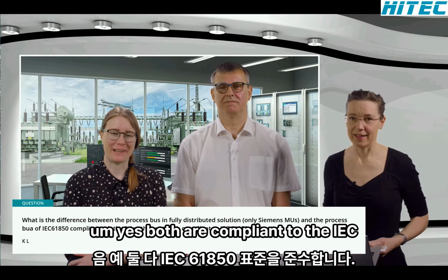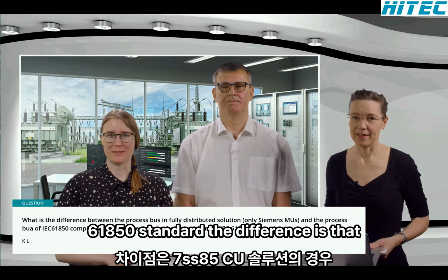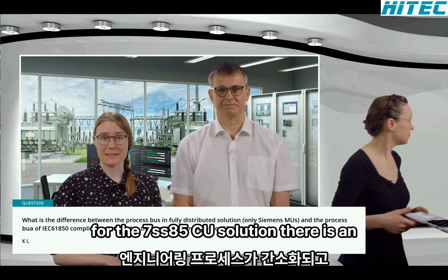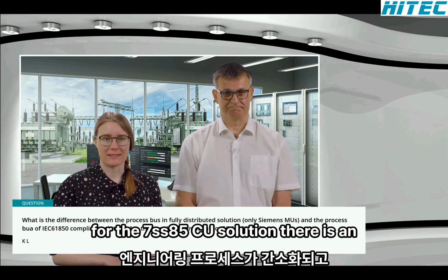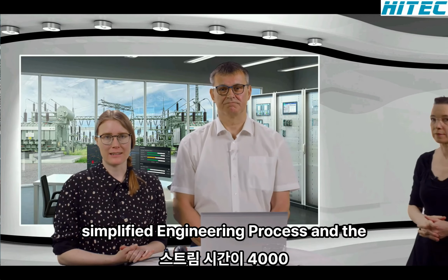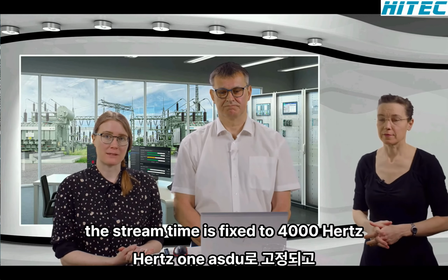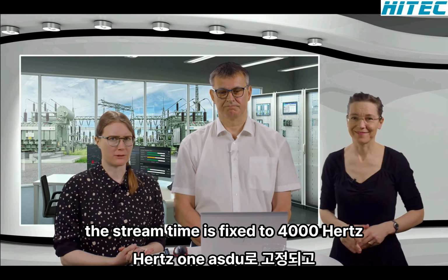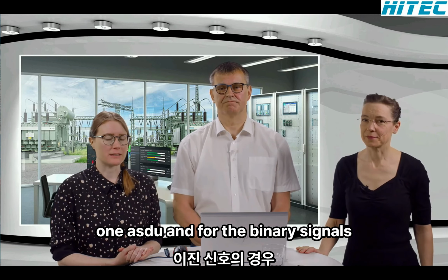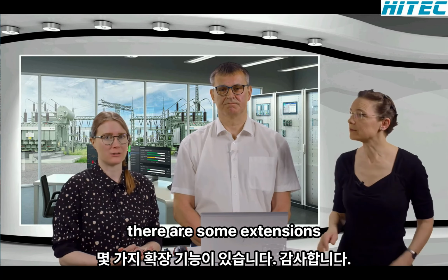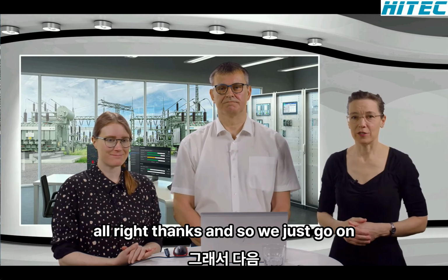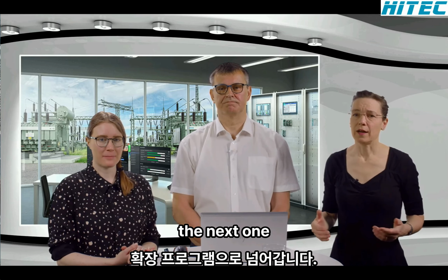Yes, both are compliant to the IEC 61850 standard. The difference is that for the 7SS85CU solution, there's a simplified engineering process, and the stream time is fixed to 4000 Hertz, 1 ASDU. And for the binary signals, there are some extensions. All right. Thanks.